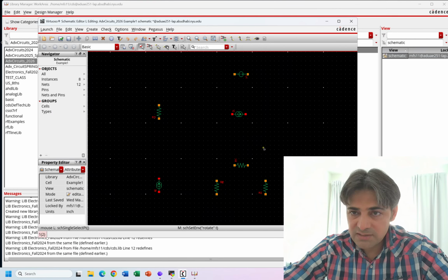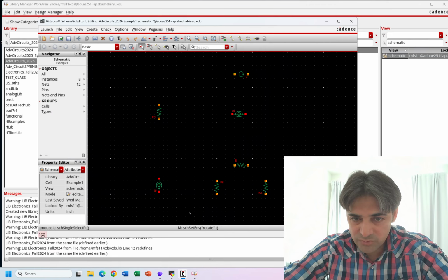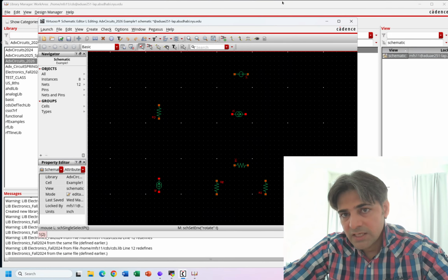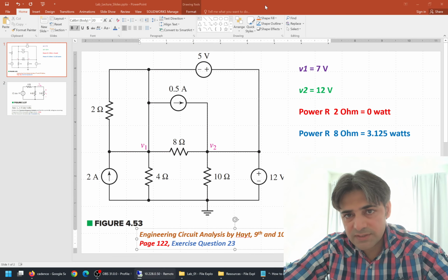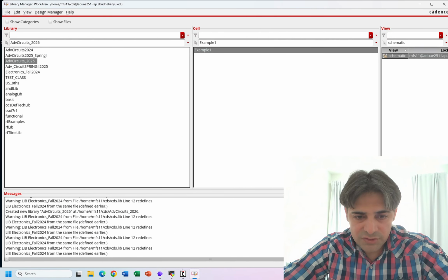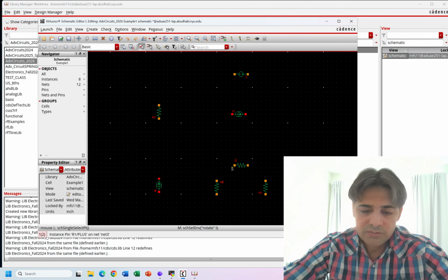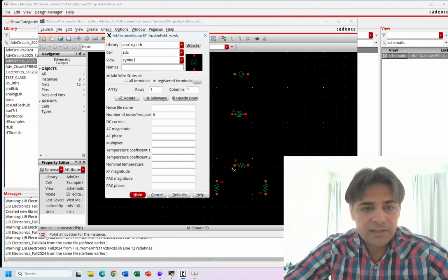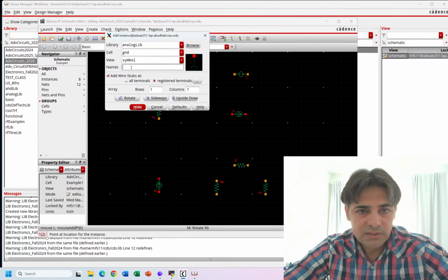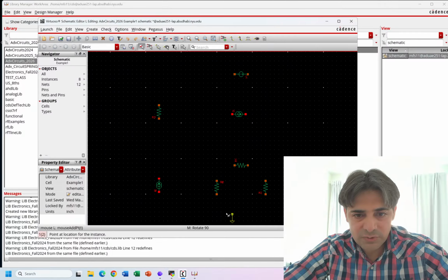But in this case, for example, we will look for the ground using the same strategy. This is the one with the most branches, and I'll choose this as a ground. This is also defined within the circuit diagram, where here is the ground. All right, so I'll instantiate my ground. Instantiate with I, and then I'll hit G and D for the ground. Yes, ground. Ground is here. I'll just put it over here.